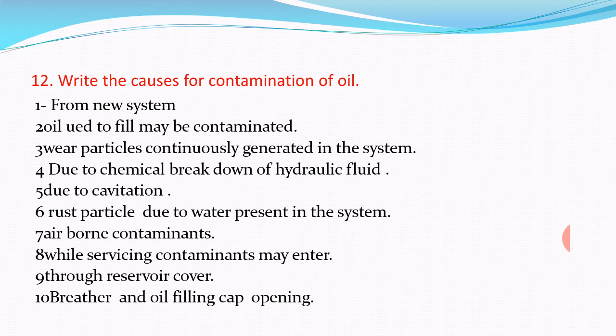For this contamination, what are the causes? First one is from a new system. Once the product is brought from the factory, it already has some metal particles due to machining, etc. So a new system already generates contaminants, and they will mix with the oil and cause contamination.